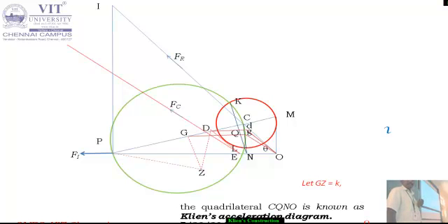You know G point, so you have to draw one vertical line. Why is this vertical line drawn? The weight of the connecting rod will always act in the downward direction. The mass of the connecting rod, that is W, will be acting here. If some mass is acting, we should find out the inertia force. Some inertia force will be acting on the opposite side because of the mass. So that component you have to consider.